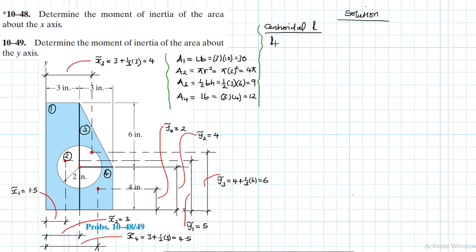So we have moment of inertia about, to start with, the x-axis, Ix1 equal to bh cubed divided by 4. This one is of course a rectangle, so we know this is the centroidal moment of inertia. b is just 3, h is 10 to the power 3 divided by 4. So this is 3 by 10 cubed divided by 4. That gives us 250.